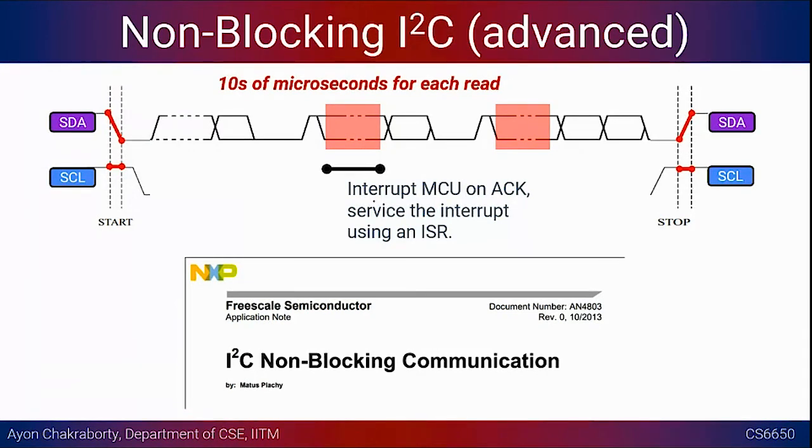Okay, they implement the interrupt service routine, and then they have implemented some kind of state machine where they declare the start condition. After that, the bus becomes busy. If the acknowledgement does not arrive for a sufficient amount of time, they will declare a fault, and so on. So it's a little bit long in terms of the algorithm. I would definitely recommend you look at it, maybe after your exam is over. I'm not going to have all these things in the exam, but for your own knowledge, you can try to look at this small variation, right?